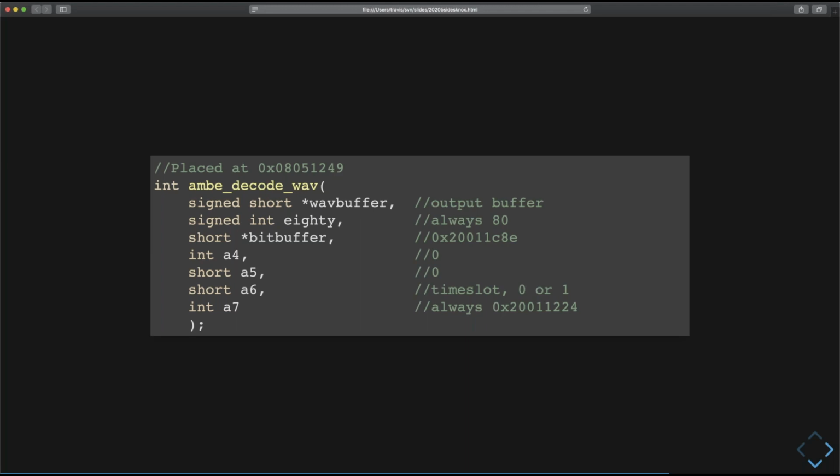And I don't have to, because as far as that function is concerned, everything that it expects in flash memory is at the correct address. And everything that it expects in RAM is at the correct address. So if I call it with the same parameters, it performs the same functions.